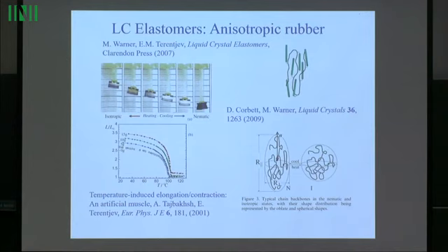So in the isotropic phase, this elastomer strip might be rather short, but then if you cool it, instead of thermal shrinking as with most materials, it will show expansion. And this expansion might be very, very large. This is one of the earlier papers on the issue. And the explanation is very simple.